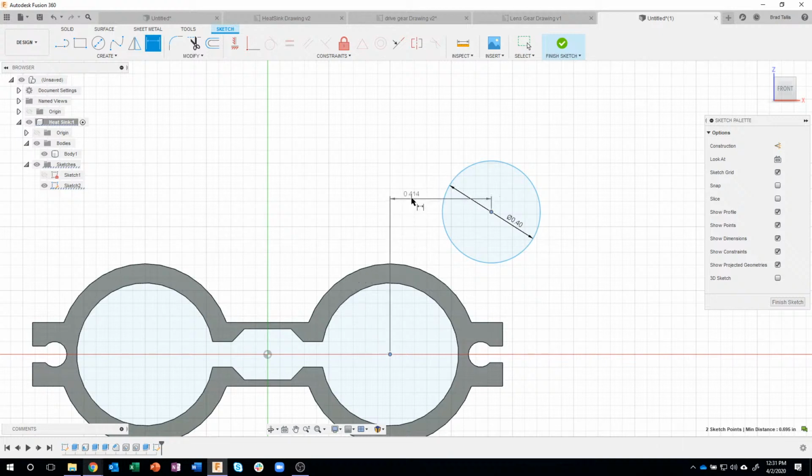If you move around, you'll get it finally to go horizontal, or you'll get it to finally go vertical, but you kind of have to know where to go to make that happen. Well, if you have a hard time with that, just right mouse click and say, I want this to be a horizontal dimension. And now you'll notice no matter where I move, it has to be a horizontal dimension.